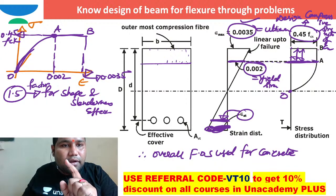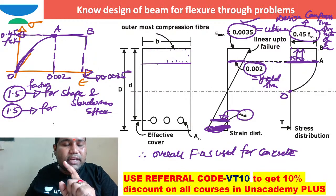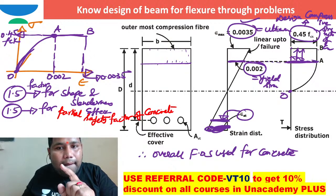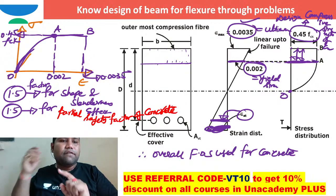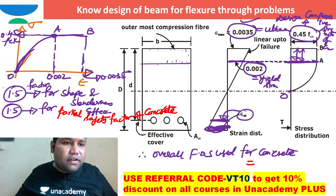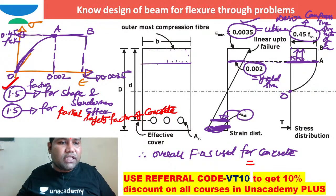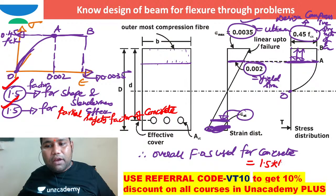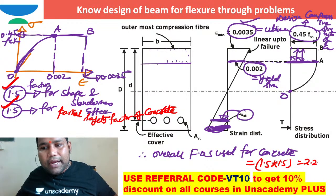Again, 1.5 is the partial safety factor of concrete. So totally, what is the overall factor of safety used for concrete? One factor of safety for shape and size effect is 1.5, another factor of safety is 1.5. So totally, 1.5 into 1.5, which is 2.25.